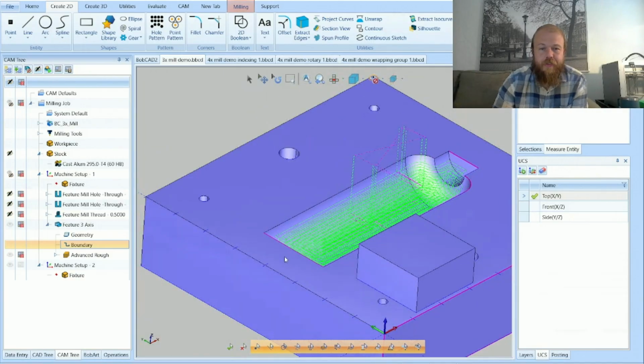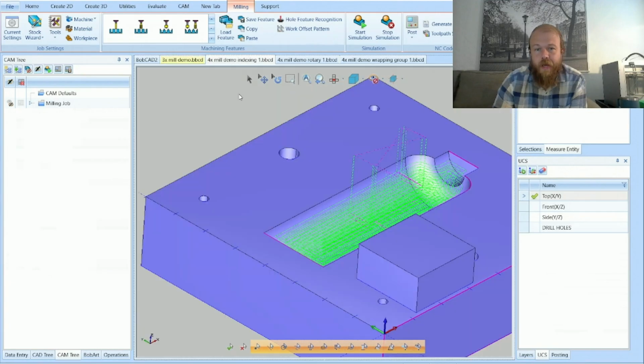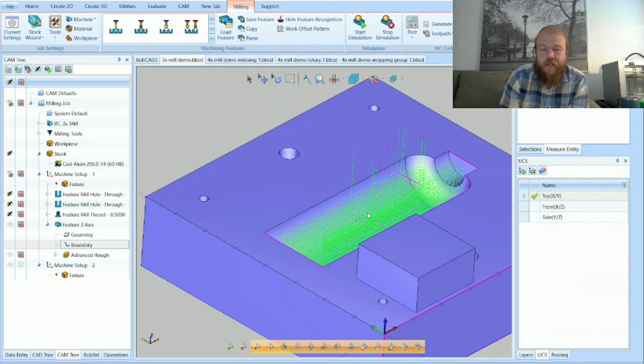That way you can offset the boundary if you need to come in from the outside and work your way in, or maybe little different boundary options than you have on your 3D model there. Contain the toolpath a little bit further inside of your pocket if you wanted to. Change the boundary by creating 2D wireframe.